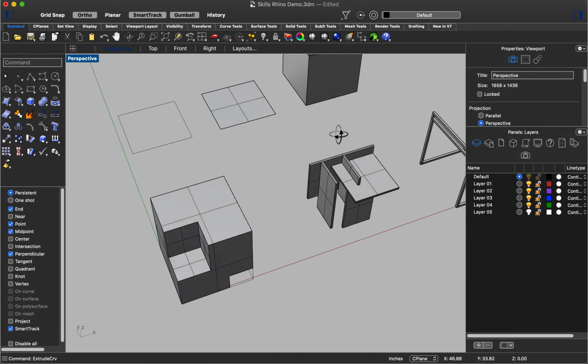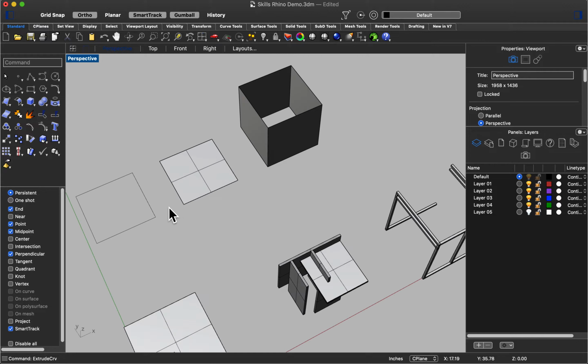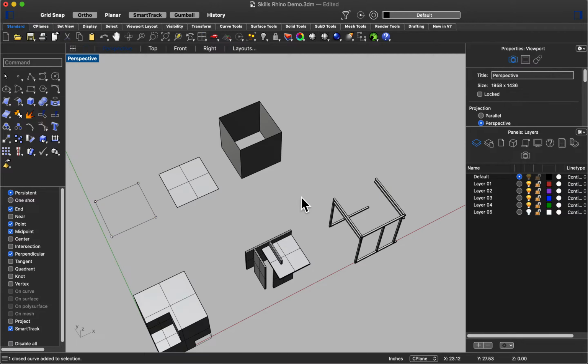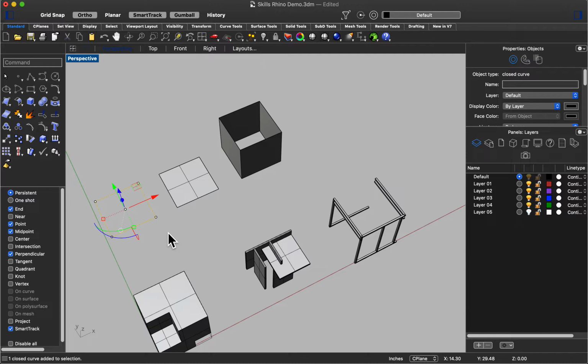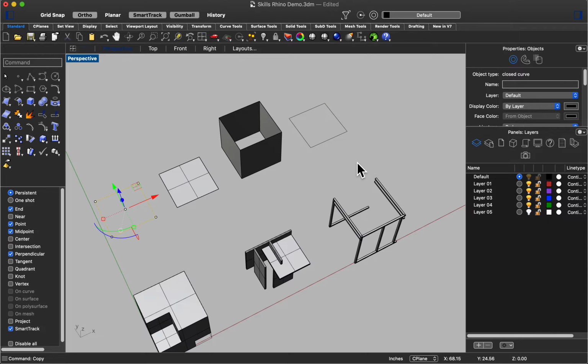I don't really want a hollow cylinder. Normally when I'm 3D modeling, I like using solid closed volumes because these paper thin tubes aren't realistic, I guess, in a way, of anything I'd be modeling in real life. Everything has a thickness to it, and this is like razor thin. So I'm going to copy that again and show you how to make a solid cube. So copy, I'm just going to move it over here, and then hit escape to finish.